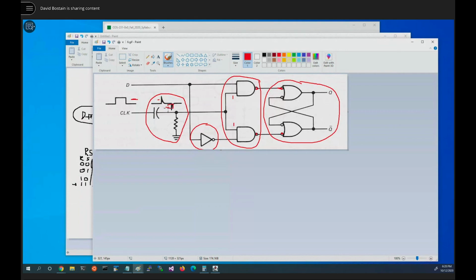Remember, the low-going pulse is basically clipped away because we don't allow in this circuit any signals to go below ground. And this signal would go above ground and then below ground, above on the rising edge, below on the falling, because that's what's happening. It's moving from 0, no change, into an upward direction. No change, then boom. So the fact it's low in the middle, low in the middle, low in the end means didn't change, didn't change, didn't change. So it's emphasizing only the point in time when there's change.